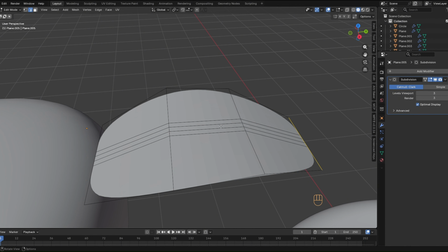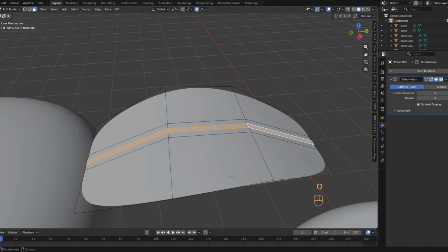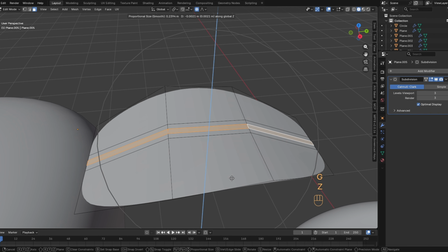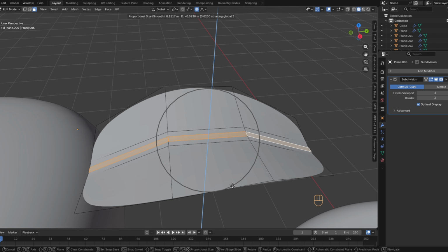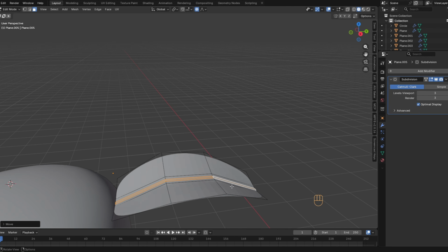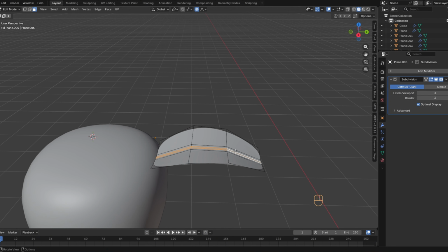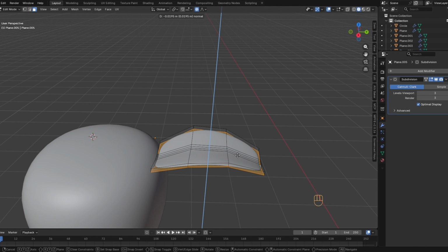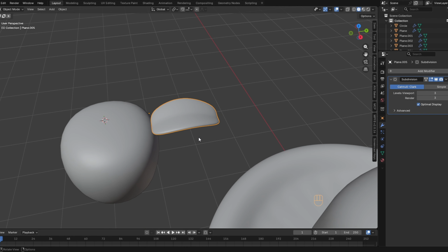Press 3 and select the 3 center faces. This shapes the leaf naturally. Switch to Object Mode and apply Shade Smooth. Then back to Edit Mode, press Tab and extrude the leaf downward with E. Switch to Top View.